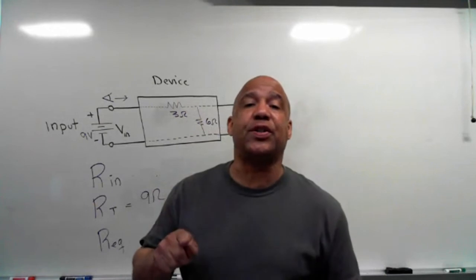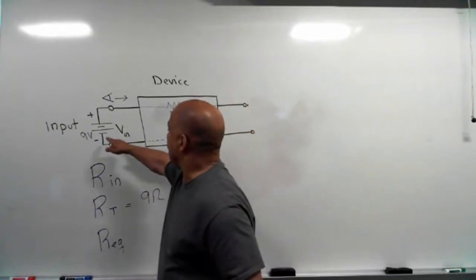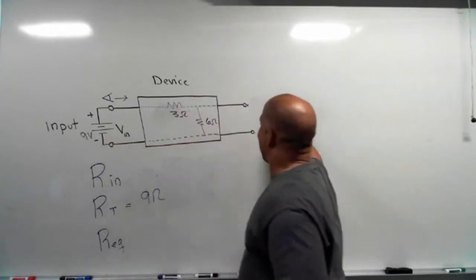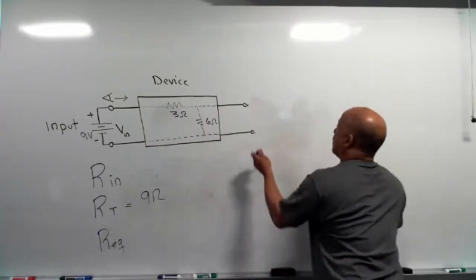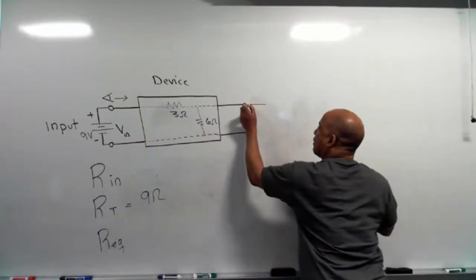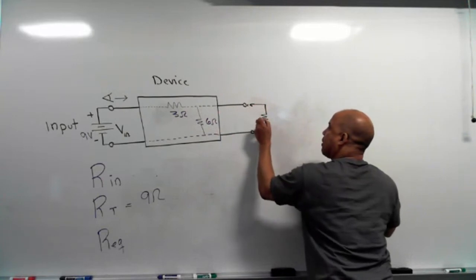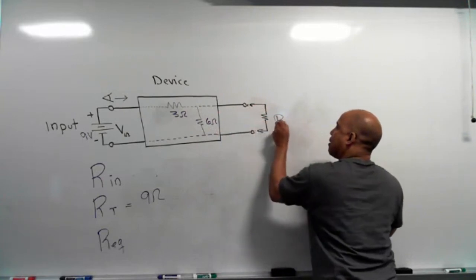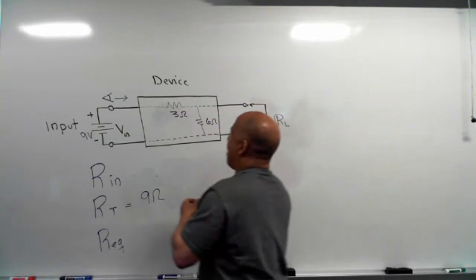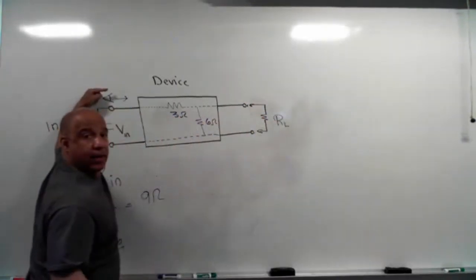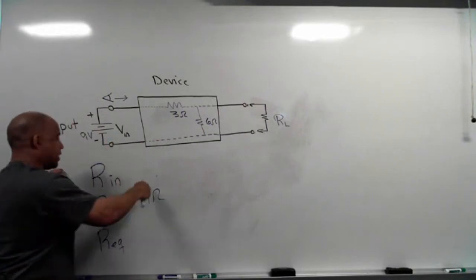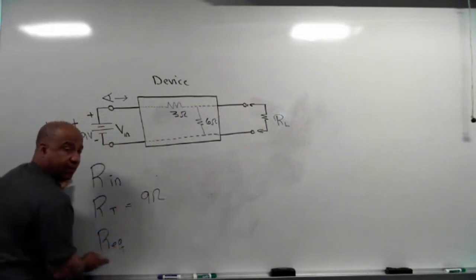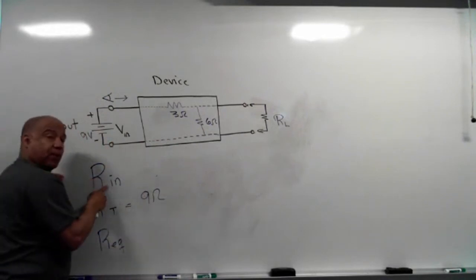Just like there's a resistance from the point of view of the voltage source, the thing I took off over here, the load, if I put the load right here, if I had an eyeball and I'm looking this way into the circuit, the resistance from the point of view of the voltage source is called the total resistance, equivalent resistance, or the input resistance.